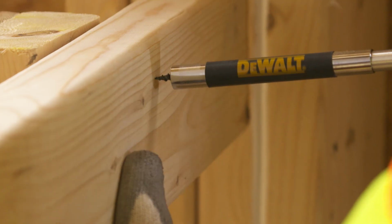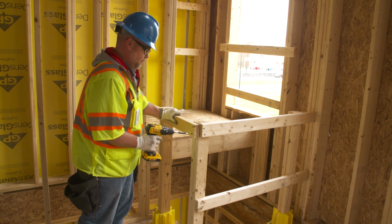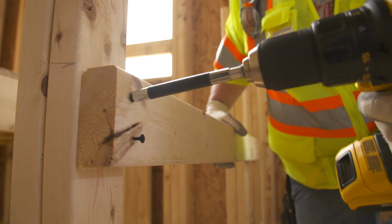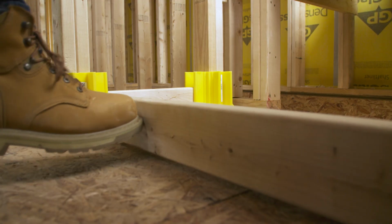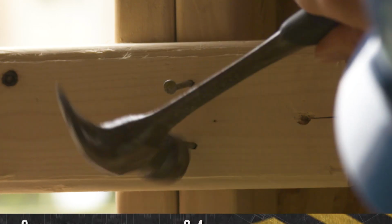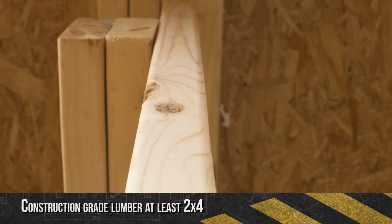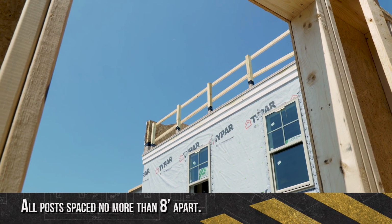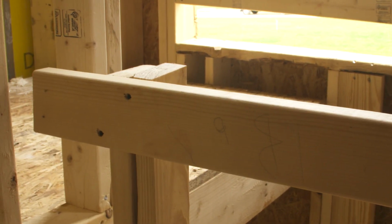Guardrails must be strong enough to resist breaking. The top rail of a guardrail system needs to withstand at least 200 pounds of force applied in any direction along the rail. Mid-rails must withstand 150 pounds of force applied in the same manner, while toe boards must withstand 50 pounds of force placed against them. For wood railings, use construction-grade lumber with the posts being at least 2 by 4. All vertical supports or posts must be installed no more than every 8 feet. Finally, guardrails must not have any rough or jagged surfaces that could cause punctures, lacerations, or snagged clothing.